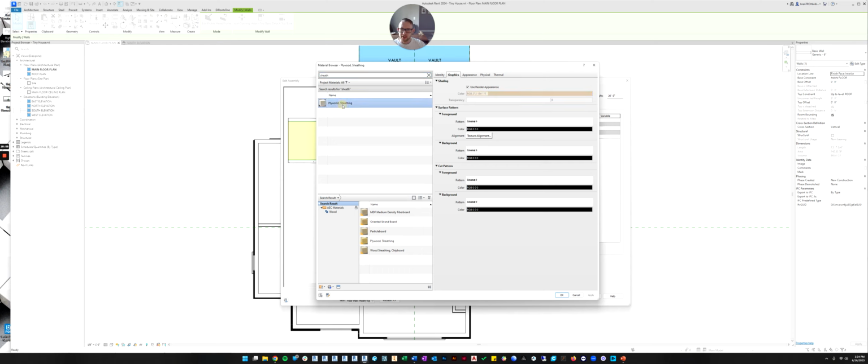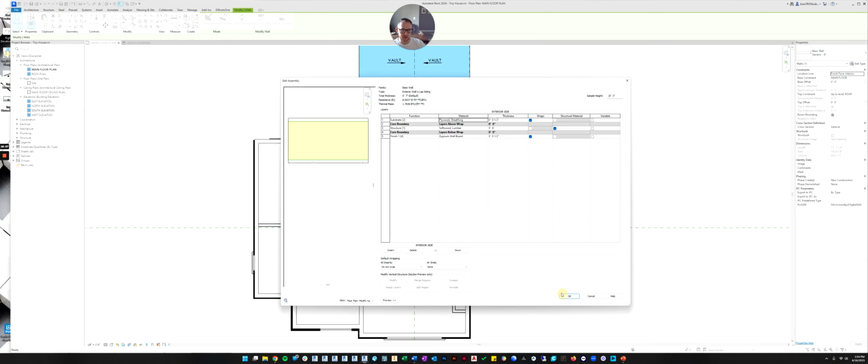Yeah, plywood sheathing. So let's click that and click OK. And then let's put on the last layer. Technically, you can also put in the weather barrier. On brick, there's technically an air gap between the brick and the stud wall. It's up to you to figure out how it's assembled. For us, we're just trying to get the wall to kind of look right on the outside.